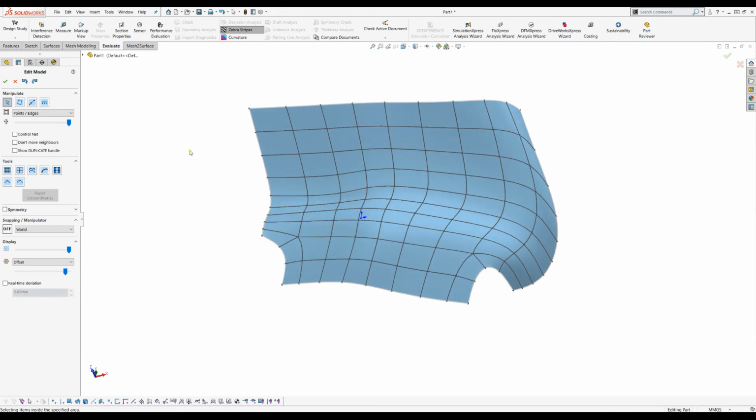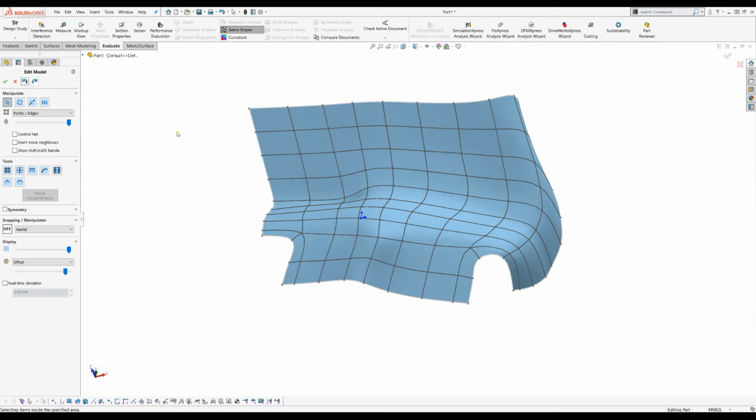The problem is that it changes the shape. If you see later on the mesh, this may deviate from the results and you may lose accuracy. So you compromise, you get a nicer and better surface, but you don't follow anymore the reference mesh. But so it's really up to you how to use this. I will just undo this for now.